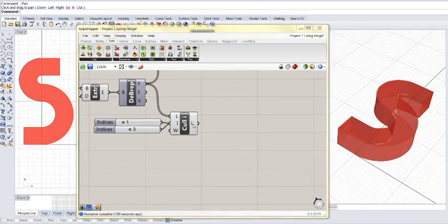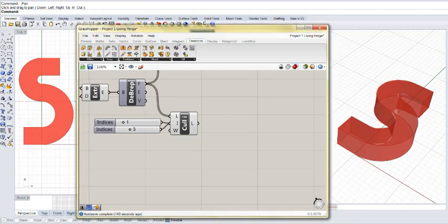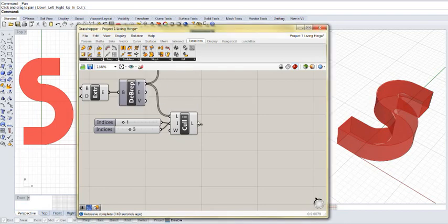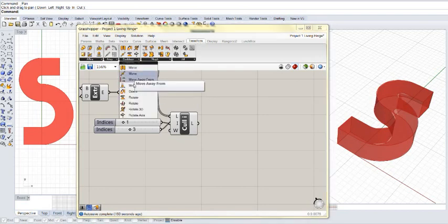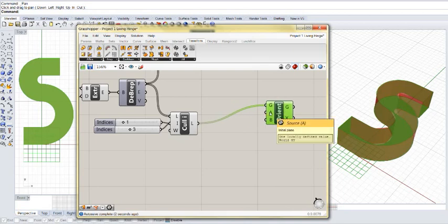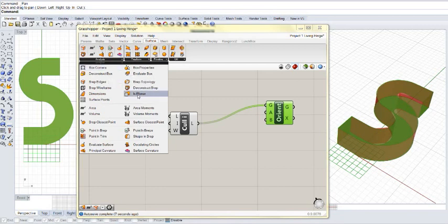To manage these surfaces and prepare them for our laser cutting files, we'll have to orient them on a plane. So let's go Transform, Euclidean, Orient. Geometries to orient, simply plug that in. Original planes, Surface, Analysis, Is Planar.